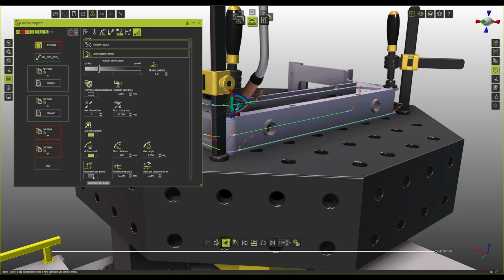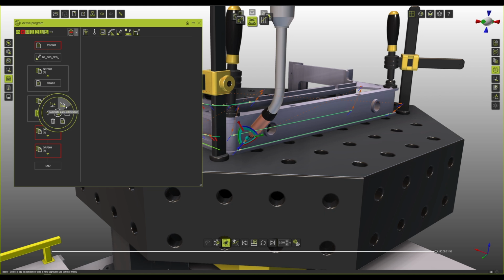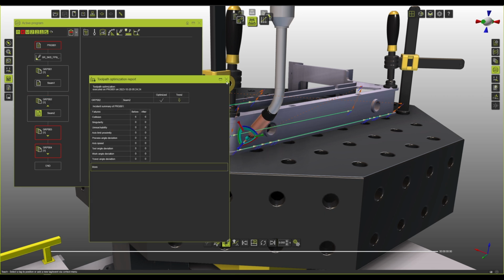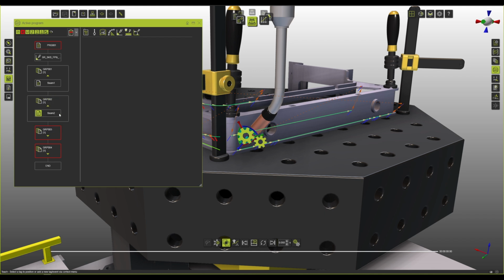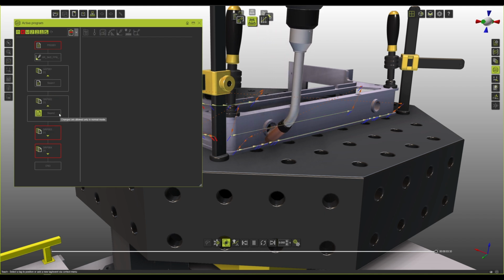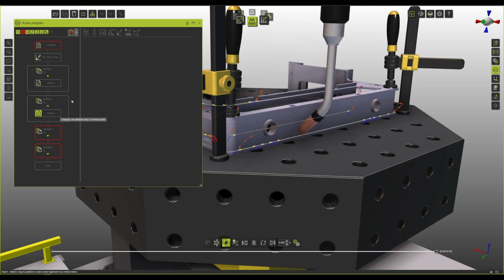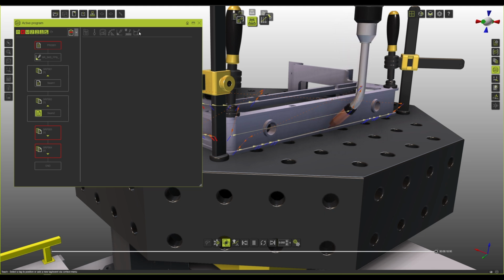But if your toolpath is long and you only have compromises in very small sections, you want to insert extra points. So only small sections of your toolpath have a decreased quality, and most of it keeps the highest level of quality. You can decide if you want to insert more points or not, but I would say in general, the motion check is always something good to have. The motion check by default has some settings that it will check every 1 millimeter and every 1 degree of motion of the robot. I would say for the processes that I've seen, this is working perfectly fine.